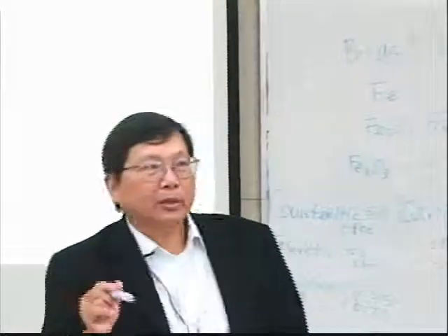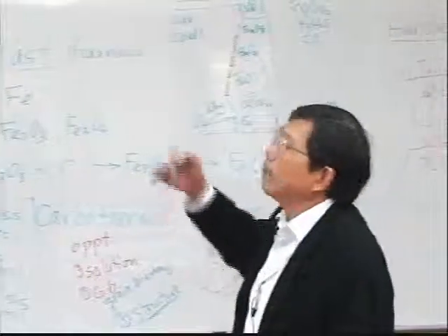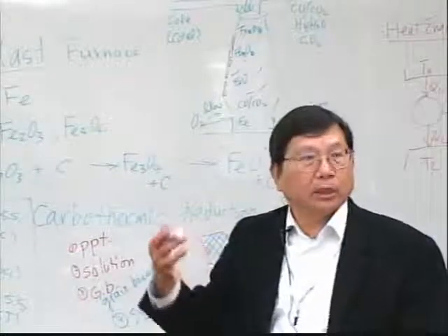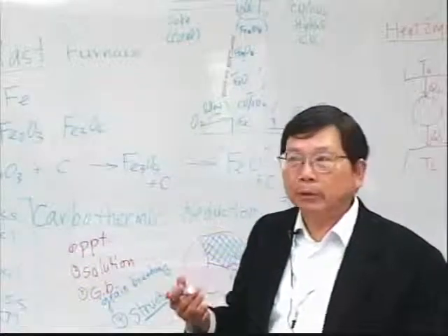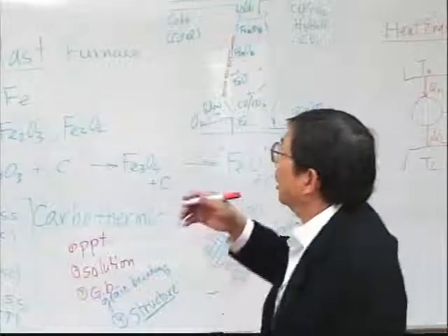So the purpose for making ceramics into composite is not to make it stronger, because ceramics is very strong already. Ceramics has very good mechanical property. It is just that it is too brittle, no ductility. So they try to make composite material for ceramics to increase the ductility, to increase the toughness. That is the objective of ceramic composite material.